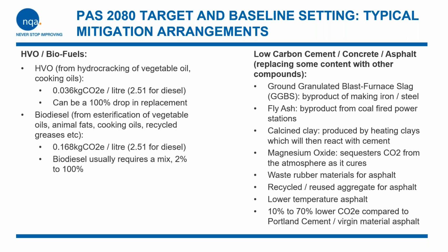It's slightly more expensive. Something similar for biodiesel there as well, and much lower, usually a little bit more expensive as well, and needs mixed in with existing diesel. But from a site operation point of view, plant generators, welfare cabins, all that kind of thing, changing out from diesel to HVO can see a really significant carbon reduction.